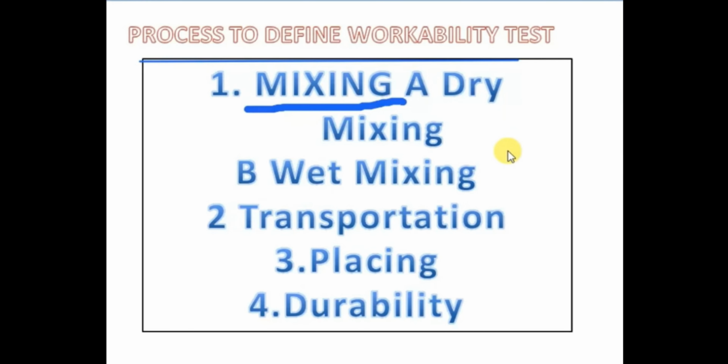So wherever we are constructing anything, it has to be transported till that particular point, and for that it is important that the transportation should be such that the water should not be excessive. In case the water is excessive, we will be throwing that water out and losing the cement part of the mixture. Hence, we will change the ratio of it.